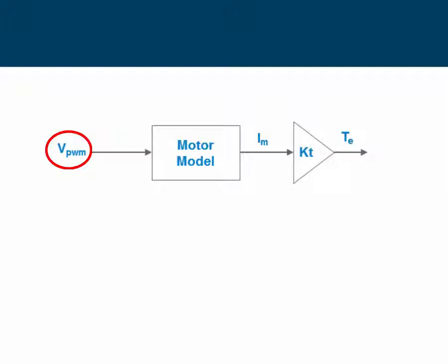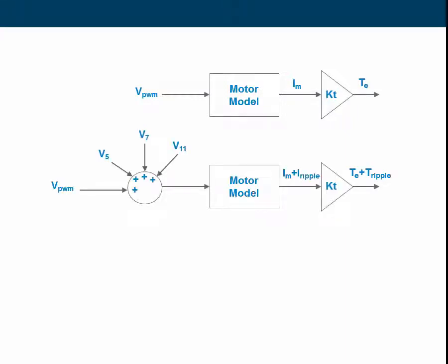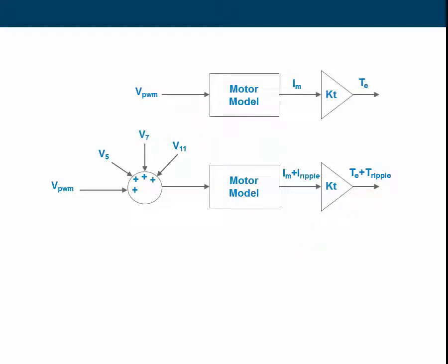The dead time in effect injects an approximately constant magnitude error voltage that changes sign when the current in a phase leg changes direction, and so step changes occur in the motor line-to-line voltages at the points where line currents cross zero. This creates harmonics of the sinusoidal fundamental voltage, which in turn generate harmonic currents and torques in the motor. This is a particular problem for larger low-impedance motors used in open-loop drives, where the harmonic currents can be significant, resulting in low-speed vibration, torque ripple, and harmonic heating.